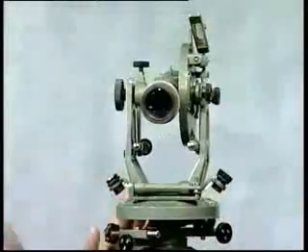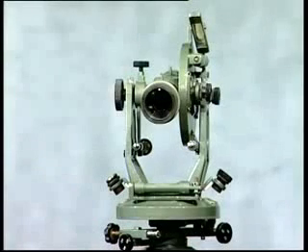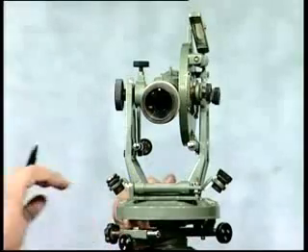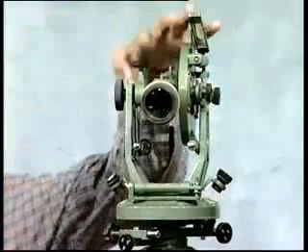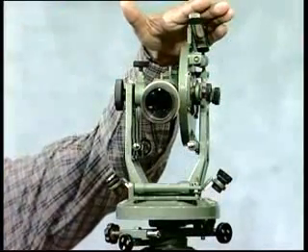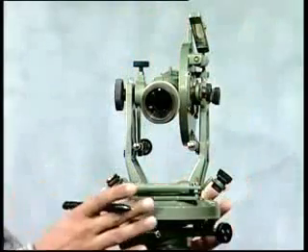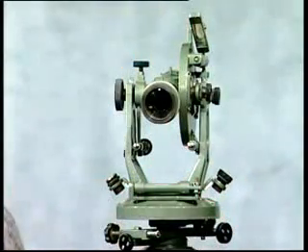In the case of the theodolite, we saw that it is really a very good, very useful instrument in surveying, and we can carry out the horizontal and vertical angle measurements. We saw the various parts of the theodolite, starting from the tripod, tribrach, leveling screws, horizontal circle, index arm, and so on, up to the telescope and the mirror here, altitude bubble, everything. Then we saw how we can take the observations using the vernier theodolite.